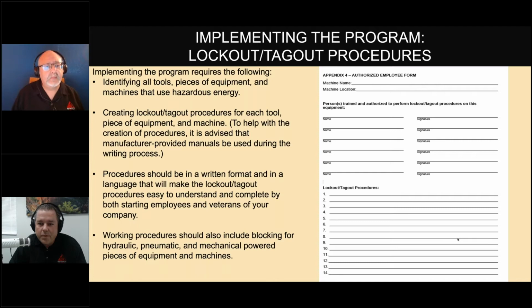Absolutely, absolutely. For example, block out, even like if you're working on a forklift and you have to raise the forks, there's got to be some way to block out the forks so that they can't fall. Like say if the hydraulic pressure gets released, that would be a block out example.